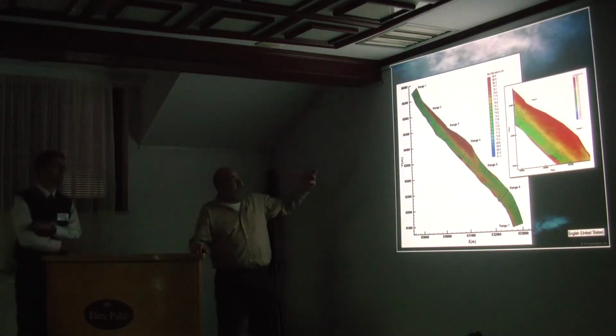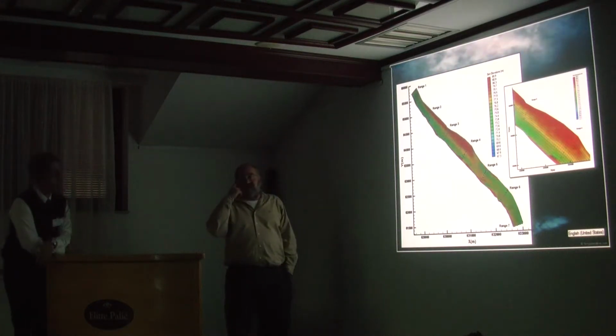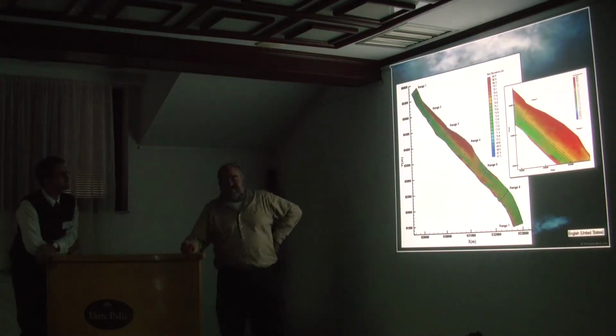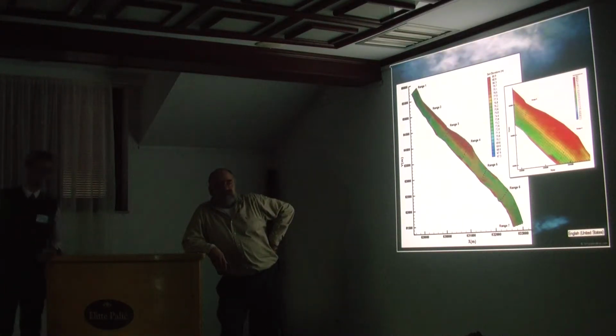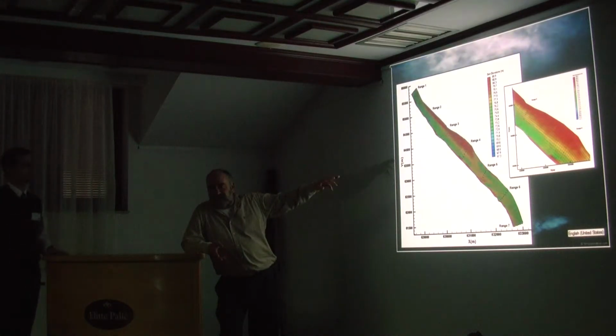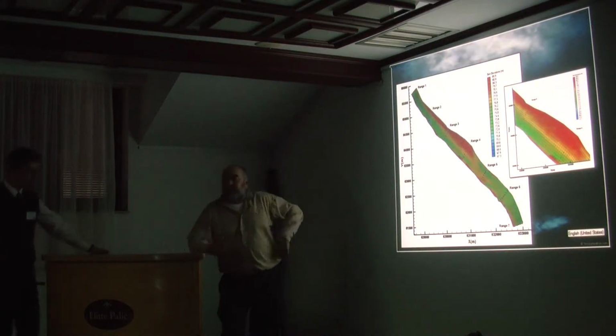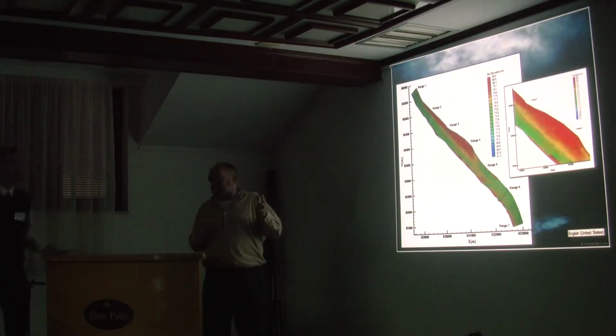This is the computational grid, that's the detail. We have several grids constructed, trying to have a fairly uniform grid. One was 10 by 10 meter cells, average size. The other was 10 by 20, and the third one was 20 by 20 meters. The results will show 20 by 20 meters, but we will use different grid sizes for sensitivity analysis eventually.